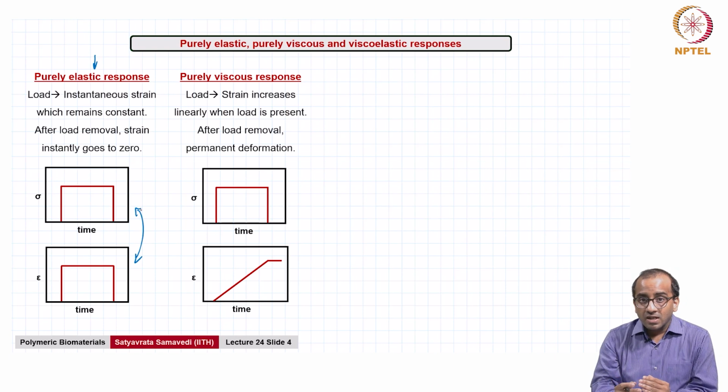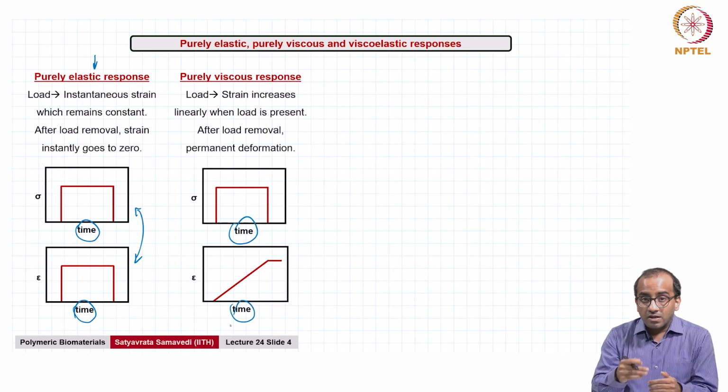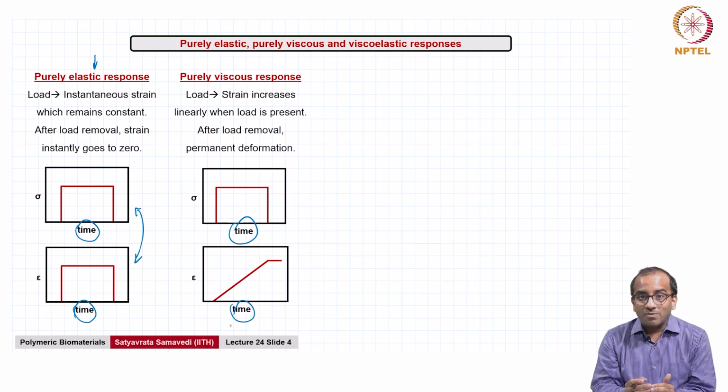And notice here, as opposed to looking at stress versus strain, which we have seen in mechanical responses in the previous lectures, we are looking now at responses all as a function of time. Because remember, once you have the viscous component coming in, viscoelastic responses are better understood as functions of time, where deformations, loads, etc., all of that can change with time.